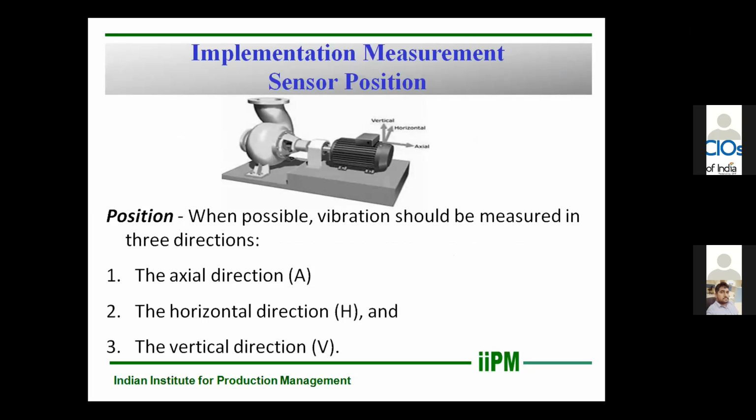So at what axis should we measure? Normally, the three axes are the most important, and after that you can choose depending upon the application. Horizontal measurement typically shows the most vibration, because the machine is more flexible in the horizontal plane. Also, imbalance is the most common problem, and it produces a radial vibration that is part vertical and part horizontal. Because the machine is usually more flexible in the horizontal plane, excessive horizontal vibration is a good indicator of unbalance.